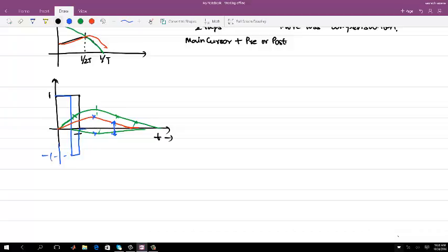Okay. One last thing about equalization on the transmitter side is that it's easy to implement, because the bits you have are well-defined positive or negative signals which you need to equalize. You have the whole bit pattern on which you apply the equalization. The problem is that there is a finite supply on the transmitter side. A finite supply leads to reduced amplitude on the receiver side, because you cannot amplify the signal on the transmitter side beyond a certain limit.